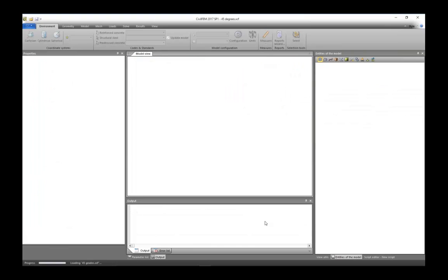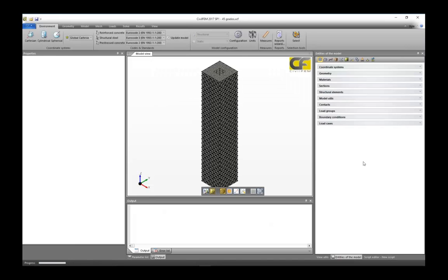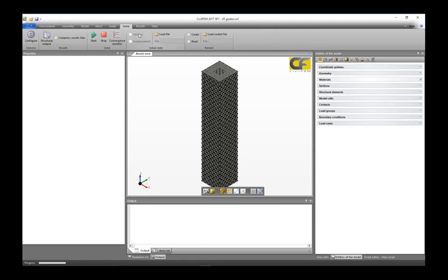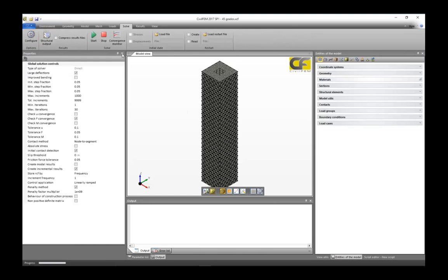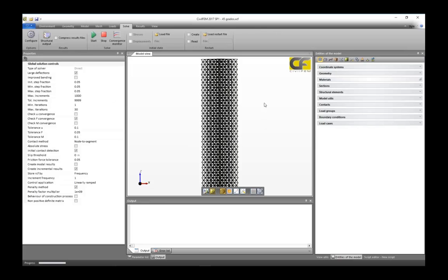By default, CivilFEM always analyzes a linear static analysis, but you can always go beyond. In this case, we started with a linear case and proceeded with a check and design, and now we will add the non-linearity of material. In this case, for steel, but we can do it as well for concrete.